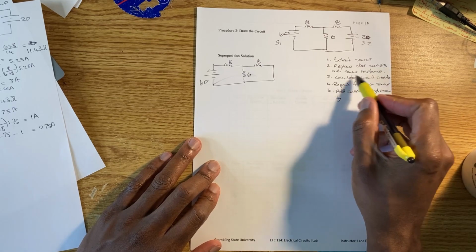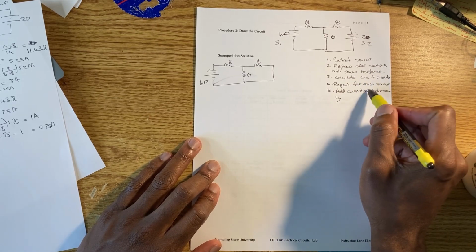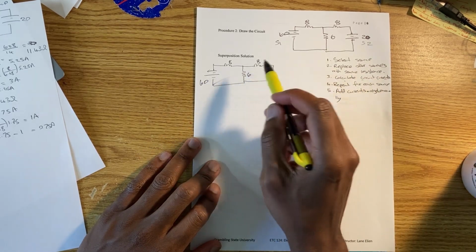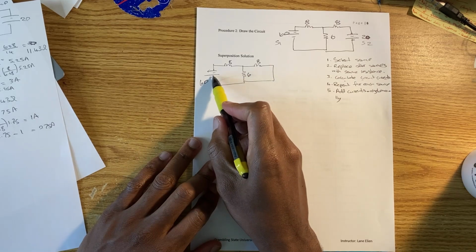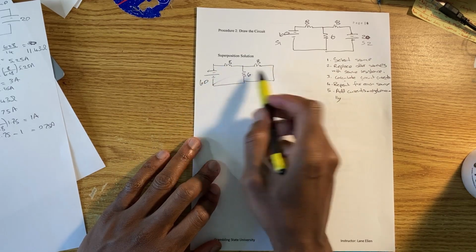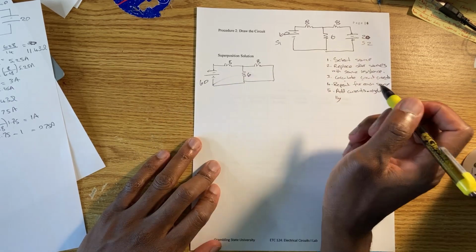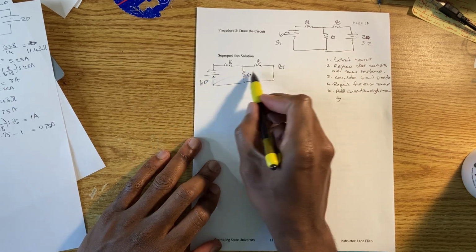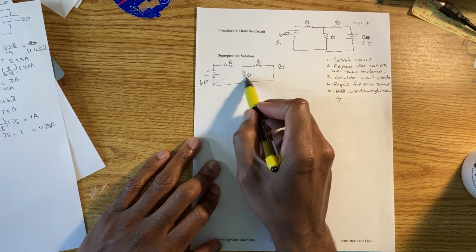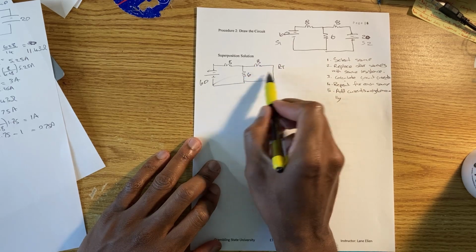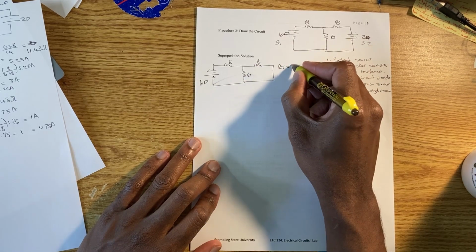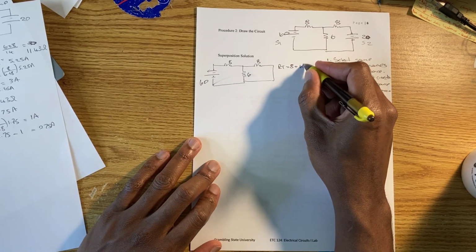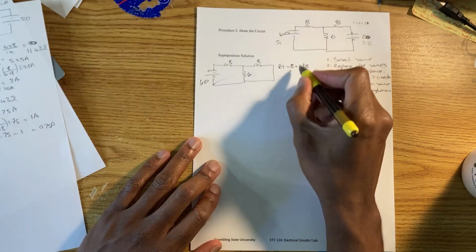The first thing I need to do is calculate the circuit currents. To find the total current in this branch, we need the total resistance, RT. From this perspective, this one is in series and these two are in parallel. If you take this resistor and bring it here, you can see they are clearly in parallel. So the source sees 8 in series with 6 in parallel with 8.